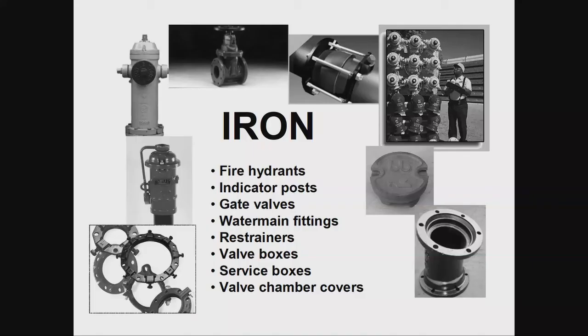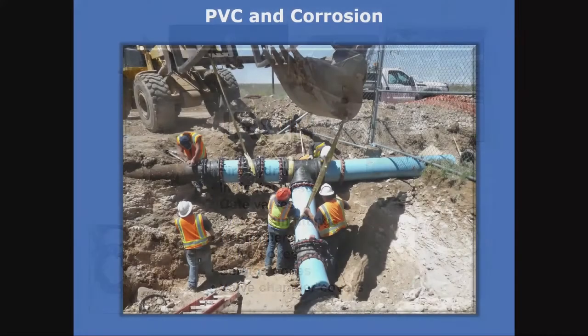So bottom line with corrosion, the industry is iron. We have to figure out and face better ways to protect that, because all these things are included. You can wrap all of these things with polyethylene encasement, all of that stuff. And nobody is immune to corrosion. As much as other materials will tell you that they're corrosion resistant or they won't corrode, nobody's immune, because of situations like this, for example. The fittings are not protected. The corrosion doesn't know the difference between a pipe and a fitting. It's going to eat whatever it's going to eat.